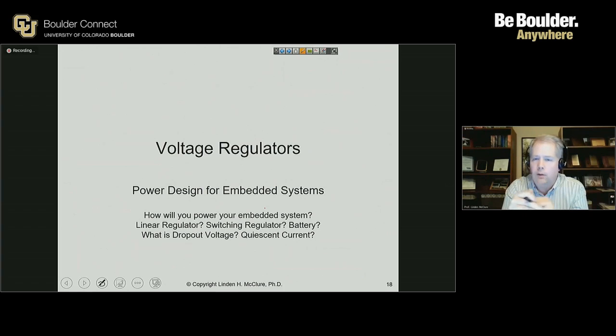So yeah, there's a good number of chips that do that these days. Not every chip has as good of a support or technical documentation as others, but if the data sheet doesn't show it, oftentimes there's an application note that the company provides which says here's a reference design, and for this reference design I've added in this capacitance.